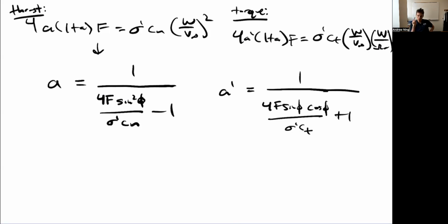But I had my two unknowns. Remember, I had two equations, got them from these two different theories, equated them. And I could solve for my two unknowns, which I've done. I can solve for my axial induction factor and my tangential induction factor. The problem is this, though, is that these are not actually explicit because